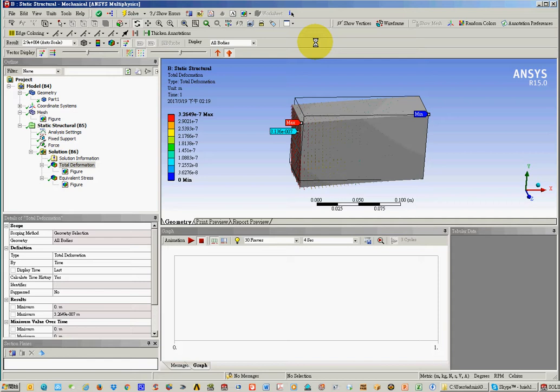This is very important: the structure of CAE analysis is always the 6 steps: the geometry, the material, meshing, boundary conditions and loading, solving, and also the result. These steps apply to all CAE analysis software, for example ANSYS, Nastran, Cosmos, SolidWorks Simulation, and also Comsol. All general-purpose CAE analysis software applies this 6-step structure. So this is very important: anyone new to this field has to memorize the 6 steps in order to be able to implement these procedures.